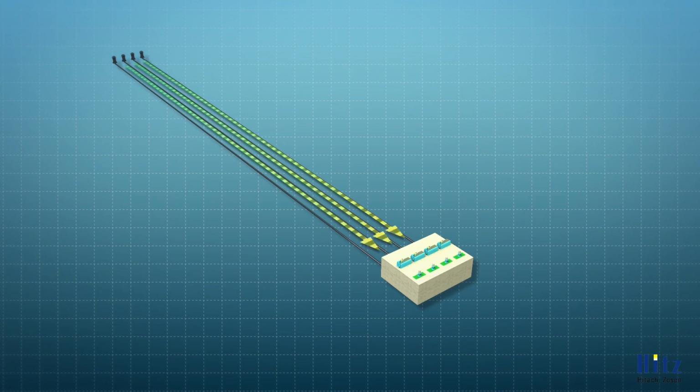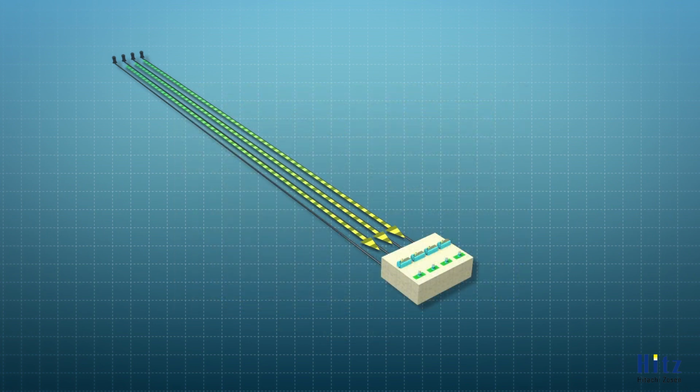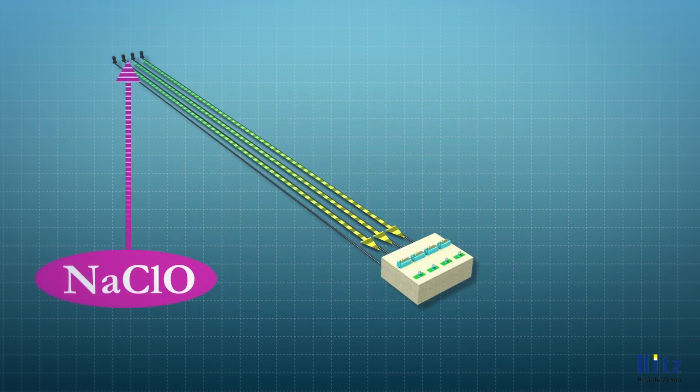Meanwhile, the intake towers and these pipelines get covered by marine macrofouling organisms such as barnacles, mussels, bryozoans, hydroids, tunicates, and serpulid worms. Corals, sea anemones, sponges, echinoderms, amphipods, isopods, nemerteans, and platyhelminthes also occur. To prevent clogging by these marine organisms, sodium hypochlorite as an oxidizing biocide is dosed.